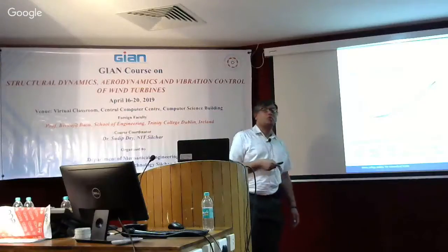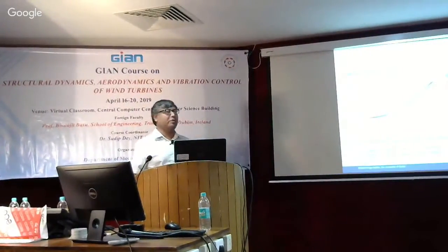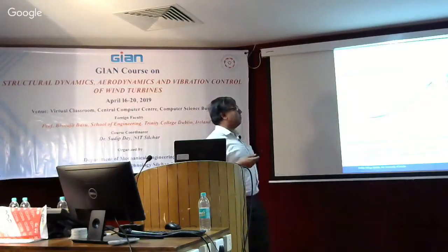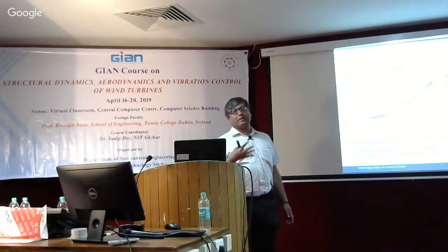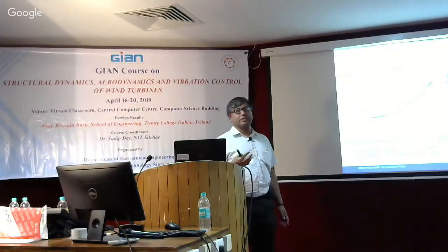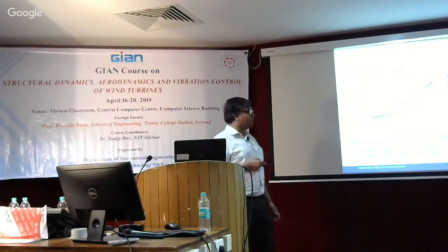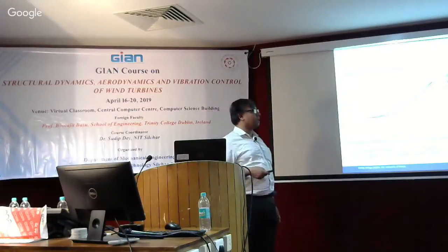It's called flap modes or B modes. And I'll actually show you a website which is from the National Renewable Energy Lab. They have some codes which you can use for getting mode shapes or running aeroelastic codes and so on. But obviously, various companies, various organizations, they have their own aeroelastic codes. Like there's a code called Bladed. There's also a code by Risø. I mean, almost all groups will have their own codes. So you can get the mode shapes, and this is also readily available.